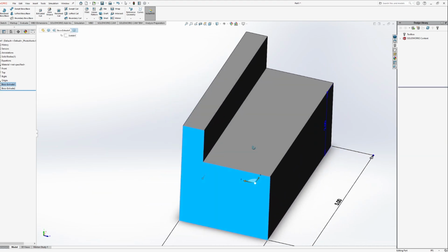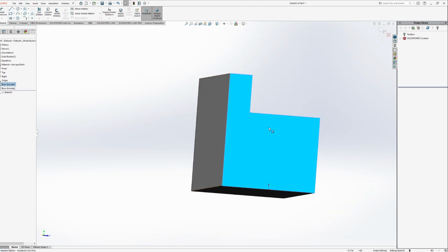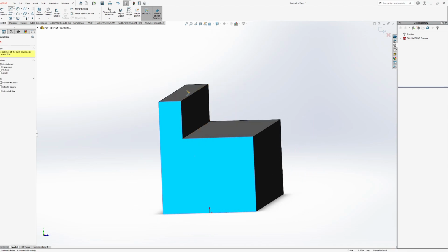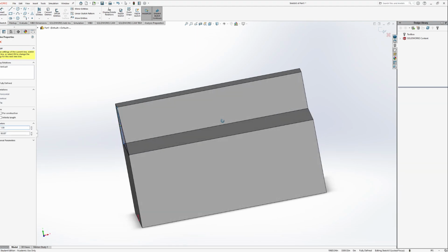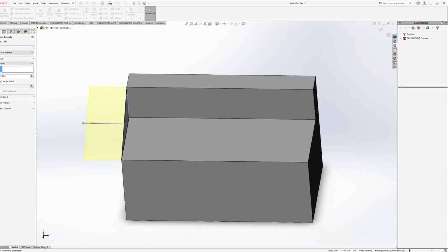The nice thing about this is that all three of the reference points for that triangular shape are really just vertices, so we don't even have to smart dimension anything, it already does it automatically. Then we can just extrude this in the appropriate direction. So flip the direction. I think it said it was 0.7 in that case. There we go.